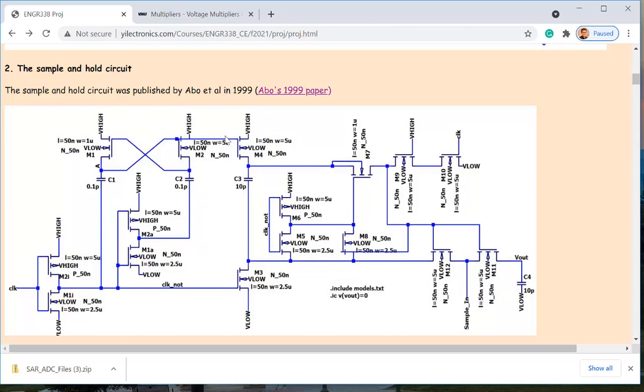Why do you want a 2 VDD to the gate here? So V high is being shorted to VDD in the future, and I need a higher VDD. Why do I prefer a higher gate voltage? It can be 2 VDD, can be a little bit less than 2 VDD, which doesn't matter. I just want to lift that gate voltage. So this NMOS is going to pass, since I want to pass the VDD signal to the terminal here, I want to pass the VDD to here.